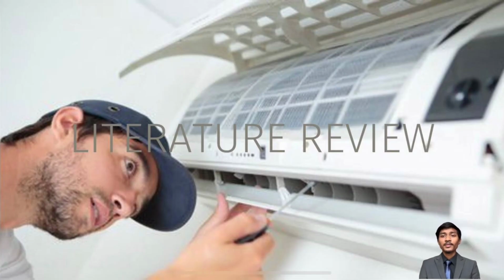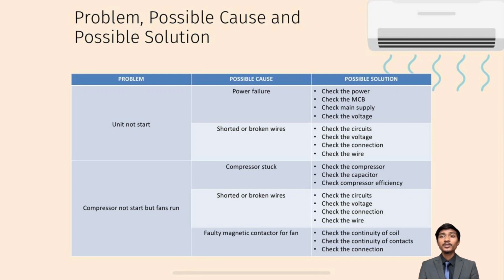Literature review. There are some problems, possible cause, and possible solution. For problem number 1, unit cannot turn on, and the possible cause is power failure and short or broken wires. The possible solution for power failure: check the power, check the MCB, check the main supply, and last check the voltage. Possible solution for short or broken wire: first check the circuits, and then check the voltage, check the connection, and last check the wire.